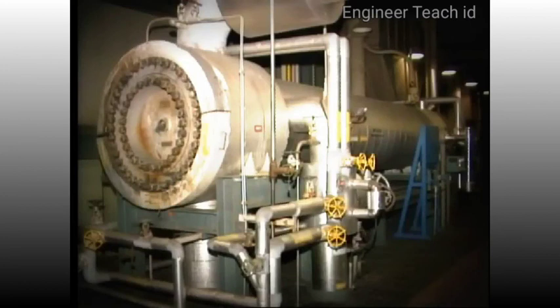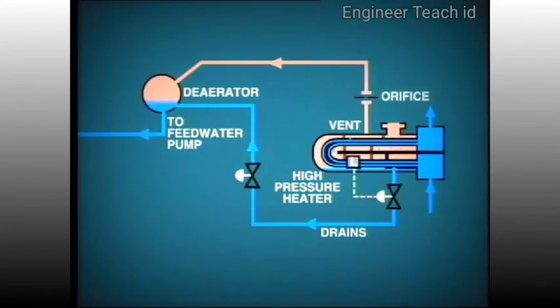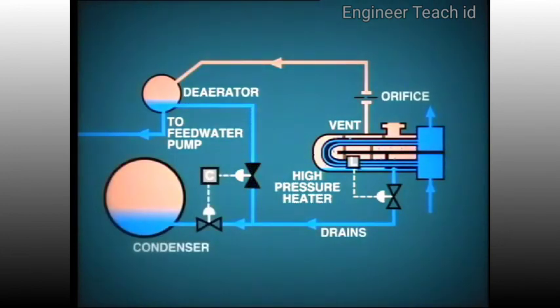The main difference is that the heat exchanger must be built more ruggedly to withstand the much higher pressures on both the feedwater side and the extraction steam side. As before, care must be taken with venting and drainage of condensate from the shell. However, in the case of this high-pressure heater, both the vent and heater drains are piped to the de-aerator, which of course operates at lower pressure. In many plants, this differential is insufficient at low load to create the flow of drains from heater to the de-aerator. Remember that in many plants, the de-aerator is located at a high elevation. To avoid this problem, the high-pressure heater drain can be alternatively routed to the condenser by automatic operation of control valves.